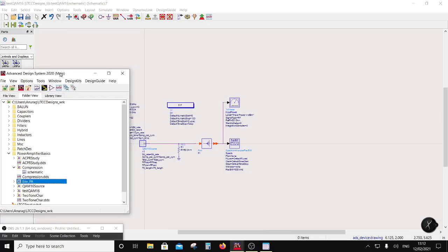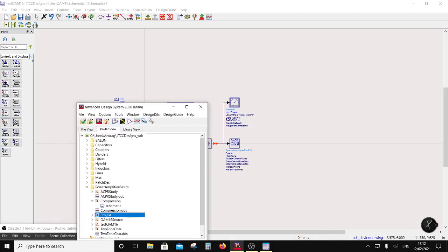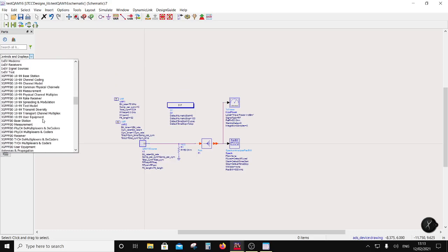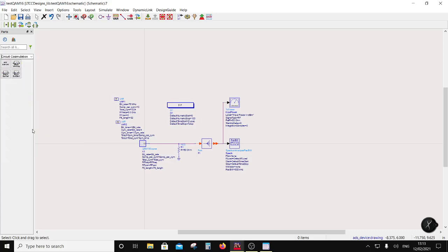But notice that we are in discrete flow simulation. We have to go to the timed. So in that case, we have to tell what frequency we are going to time scale it. So we have to go to co-simulation components, common component, circuit co-simulation, ENV. So we have to have this sampling done. So in this case, this frequency is RF FREQ, correct?